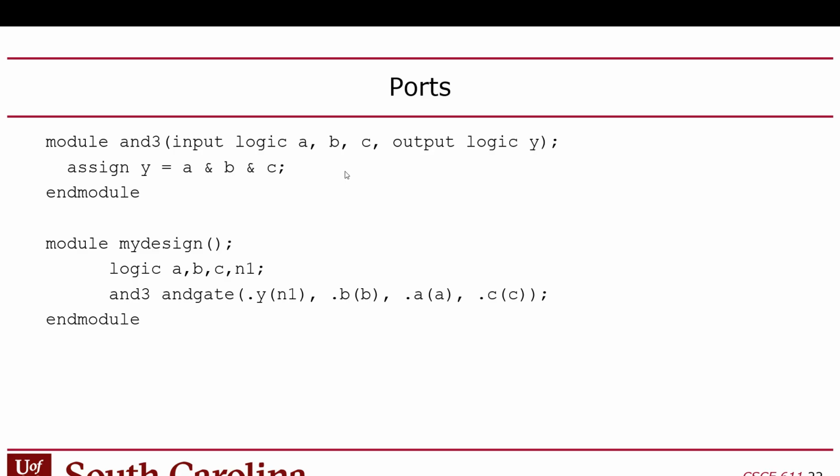The names are mangled though when they get synthesized, when they get converted to the design that actually goes on the FPGA. That's stored in a database. Sometimes you get a little insight into that with a tool called Signal Tap, one of the debugging tools. Sometimes you'll get a peek at what the tools call them, and they'll mangle the names, adding a bunch of machine-generated stuff. But at the SystemVerilog level, you choose the name. So that's the case where I can assign both of those to that wire. You could, yeah, you could do that. But that's not